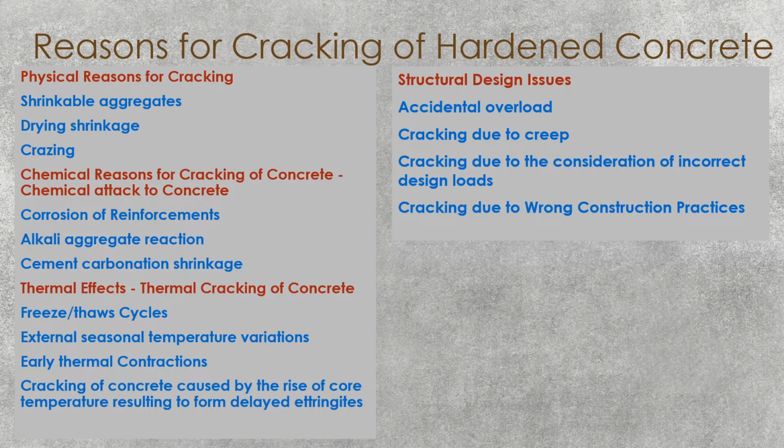Cracking due to creep. Concrete could crack due to creep effects. We have discussed this in a different video. Please refer to that, because the creep effect is a very important parameter to know when you design concrete structures. Creep will cause changes in the stresses and cause excessive deflections that could lead to cracking of the concrete.